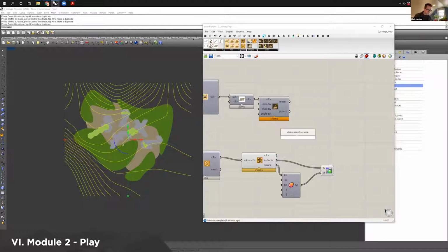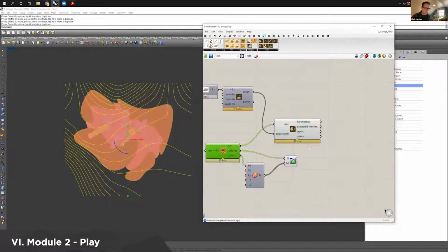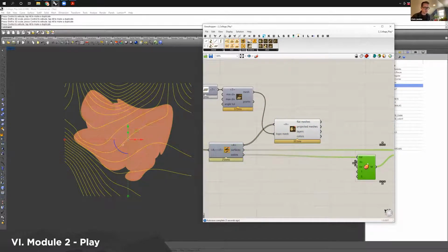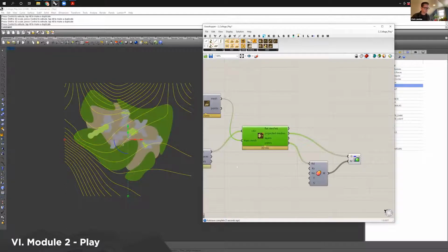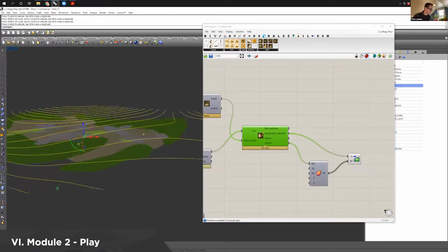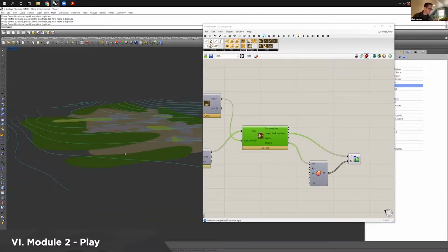Oh, we're gonna draw surface. We're gonna draw areas too. And in order to draw areas, it's looking for a mesh. It won't project to anything if you don't have it, but you can project, Control Q, and then we can preview these meshes instead. So projecting the projected meshes and the colors of those meshes. And if we look at it, it's now cutting through. Sorry, it's now set at the elevation of the landscape, right?